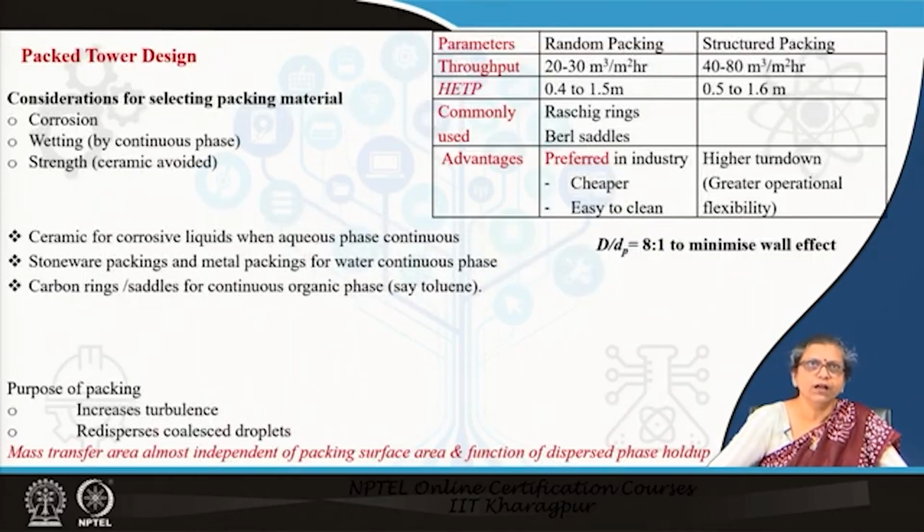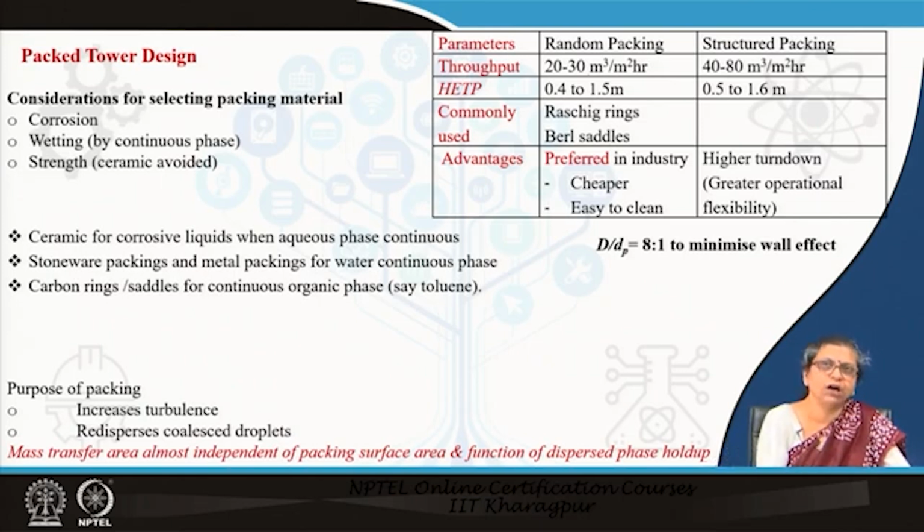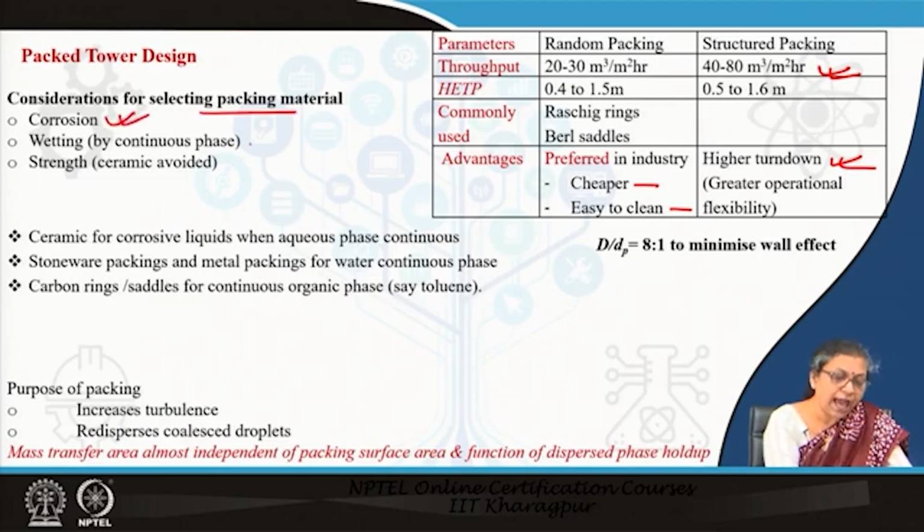After this I do not have much to say. There are certain parameters which I have put down specifically for packed tower design. Here we can use, as I have told you, both random and structured packings. It is important to remember that with structured packings the throughput is higher and the turndown is higher, yet in industries random packings are preferred because they are cheaper and easier to clean. When we select packing materials, it is important to consider corrosion, and it is desirable that the packing material is wetted by the continuous phase and has sufficient strength.